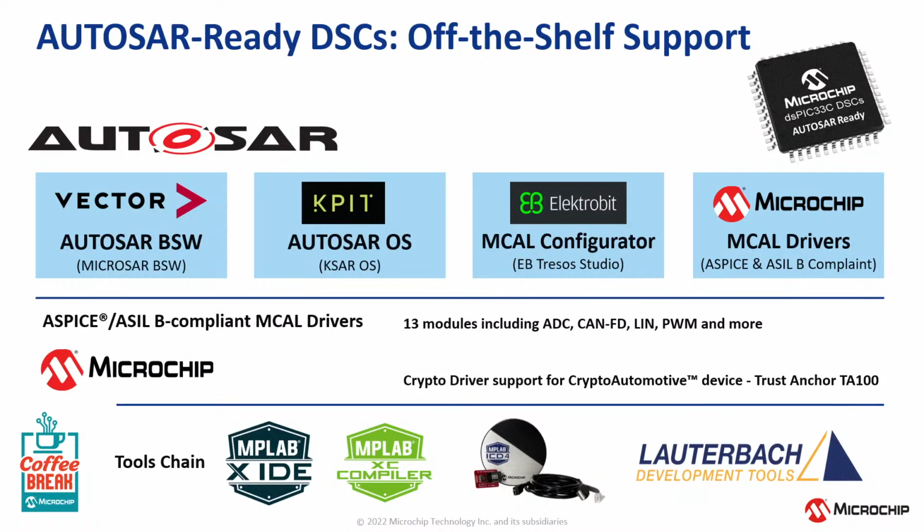And in addition also, we provide the full set of MCAL drivers, which are both ASPICE level 1 and ASIL B compliant. So we provide a full ecosystem for our devices to integrate seamlessly into the automotive environment.